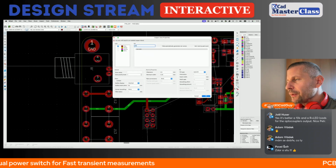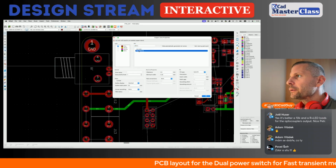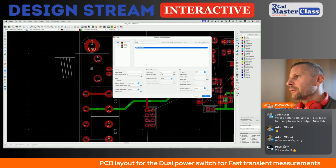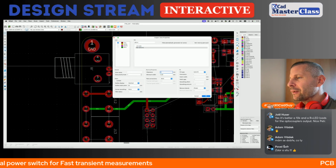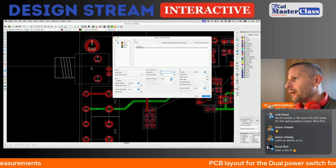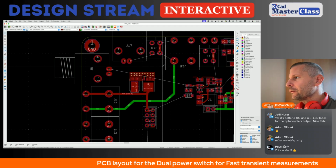So it's D10K. Yes. Solid, low priority level. Clearance will be 1 millimeter because I need some clearance around the BNC. And solid, as I said. Okay. So the polygon can go through